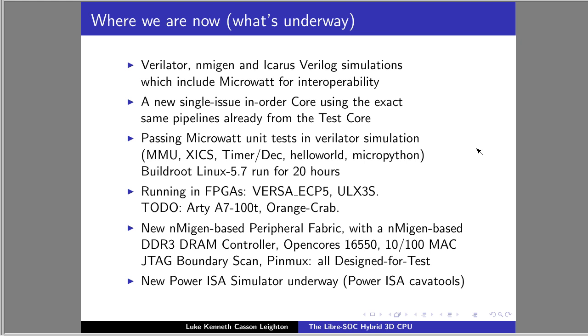You have to have a template file which contains the start of your Verilog source code and the end of your Verilog source code for the peripheral fabric of your module, into which you're going to substitute the peripherals and the interrupts and all this, and the addressing and the arbiters and the decoders and everything, so you can wire it all up.